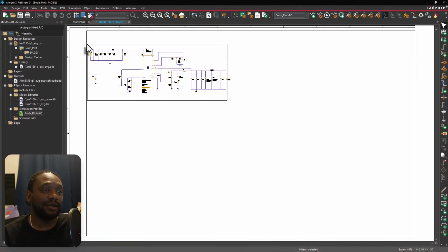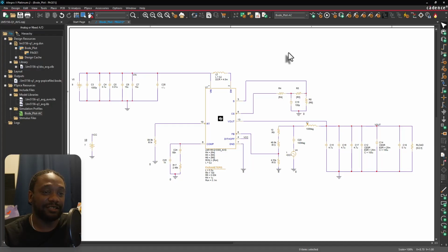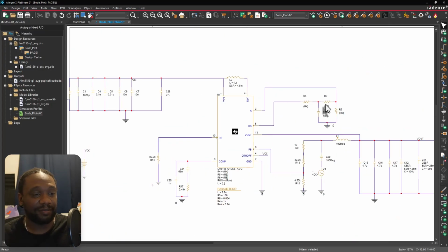So here I've taken a modified reference design from Texas Instruments just to demonstrate the feedback behavior in the AC analysis. If we go to our AC setup, I'll show you what settings you need to use. First of all, you're going to want to use the averaged model for a chip, not the transient model, to do this analysis. So I got an average model of our same chip from our other flyback circuit where we had the transient model. And we don't need to model the different switching, like a whole switch power supply.